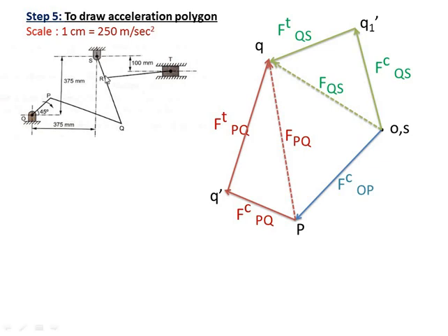Now here R is on SQ. So here also R should be on the net acceleration of SQ. Now we have to locate point R. So again we take the same image principle: SQ upon SR is equal to small sq upon small sr. Capital SQ and capital SR are the actual lengths of the links in the mechanism. So take this actual length of the mechanism.